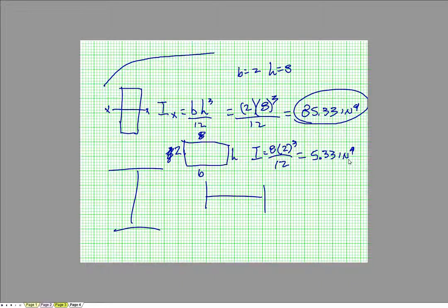So while that's not a number that will actually provide strength, you can see by the example with the yardstick why it would bend in one direction and not the other, because it has a lot more moment of inertia, area moment of inertia, or resistance to bending in that other orientation, and the numbers go along with that.